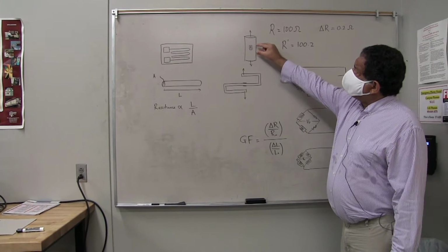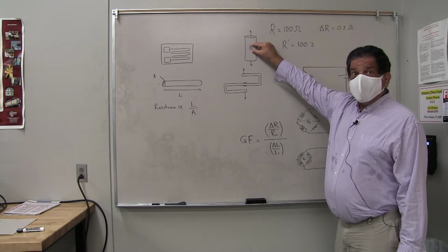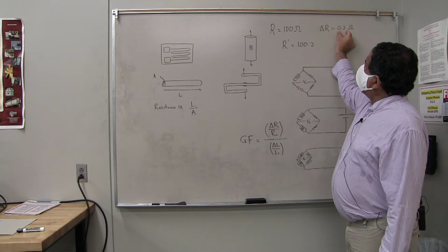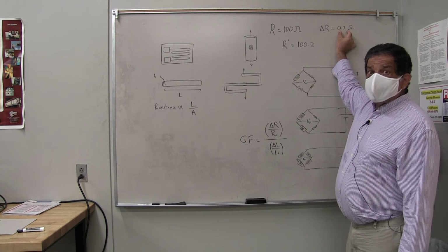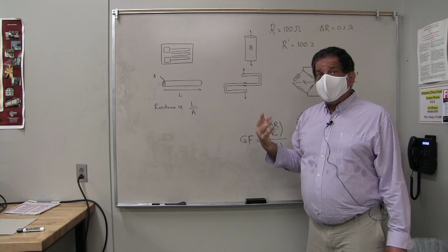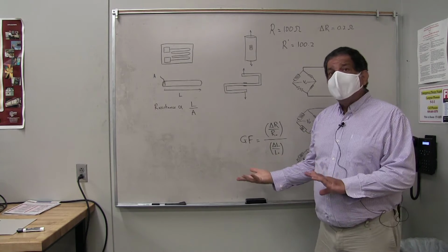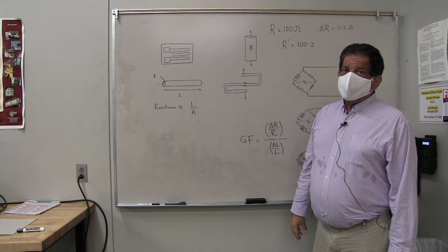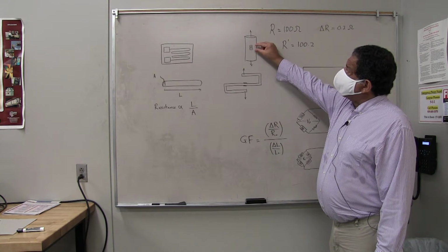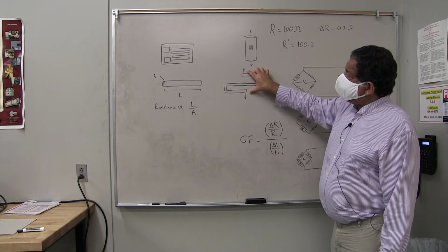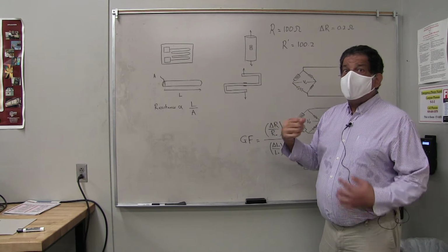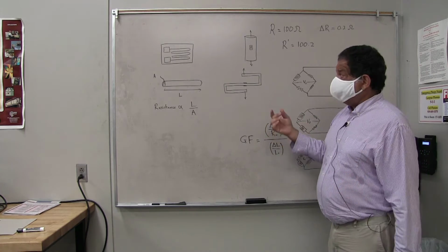So instead of just measuring the resistance straight up like that, we look for ways to magnify that difference in resistance. Okay, and there's ways that you can magnify the difference in resistance mechanically, and ways that you can magnify the difference in resistance electrically. Mechanically, what we want to do is, for the same force, generate a larger displacement in the material, and that will give us a bigger signal to measure.